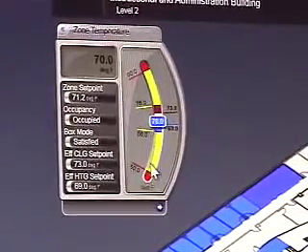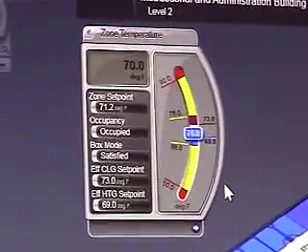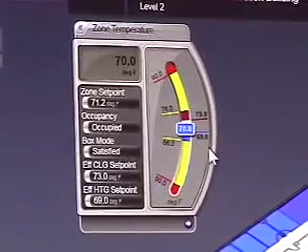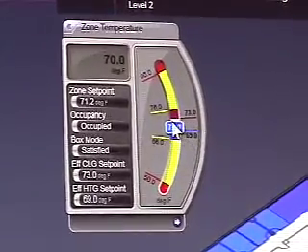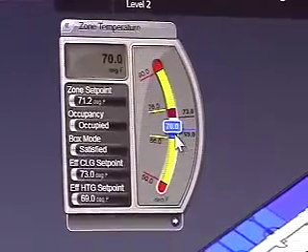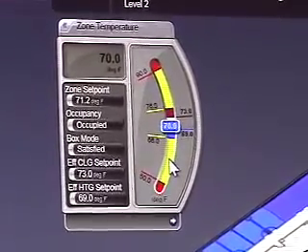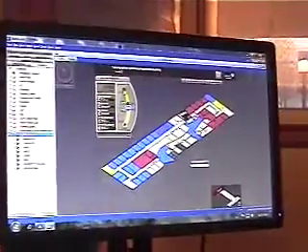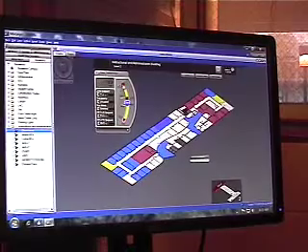Looking at this scale here, it'll give you an indication of where you're at before you approach any alarm limits or warning limits. So as you get either below set point or above this, so what is that, 76 or below 66, you'll actually go into a warning, which means, hey, something's getting a little out of whack here. If you keep going further into the red, on this one it's 50 or above 90, you'll actually go into an alarm condition, which will pop up a notification letting you know that you're in an alarm.